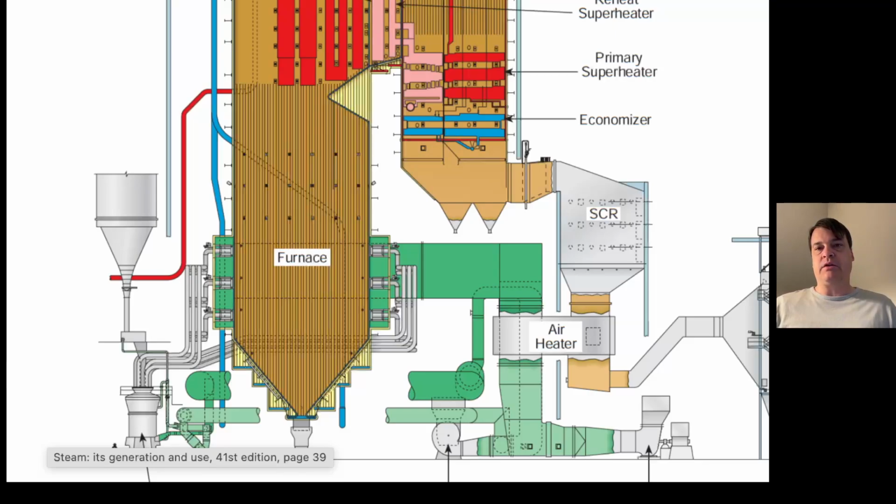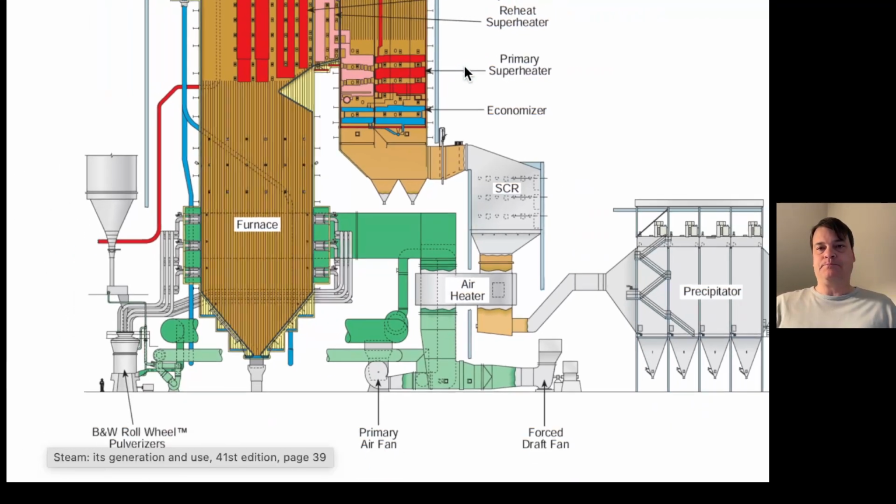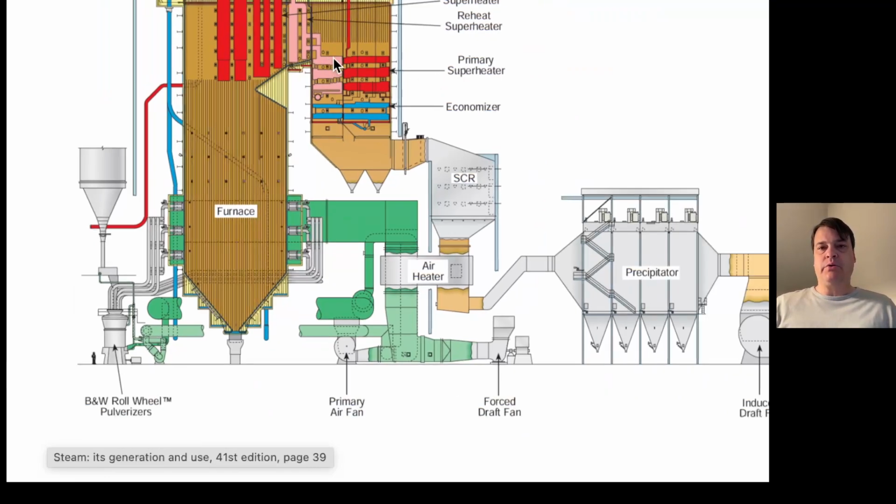and then the vapor is taken off and it runs through different kinds of pendants and in these backpass heat exchangers, and those go off to the turbines. You have different platen secondary superheaters, intermediate secondary superheaters. So we talked about superheaters with the Rankine cycle, and then you also have primary superheaters. Anyway, so this is heat exchanger that extracts the heat, and you have transfer between the turbines and back to the furnace as needed in like the reheat. You can see like the reheat superheater is listed here.